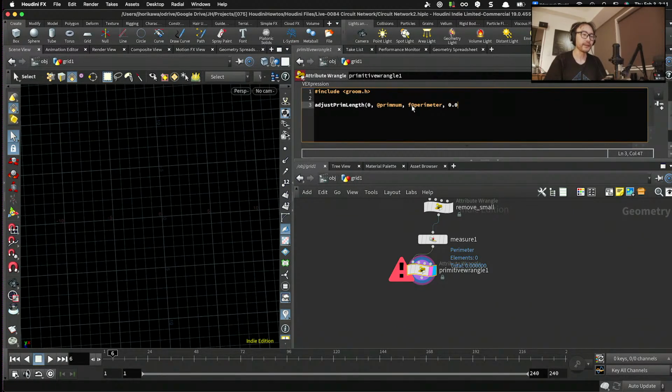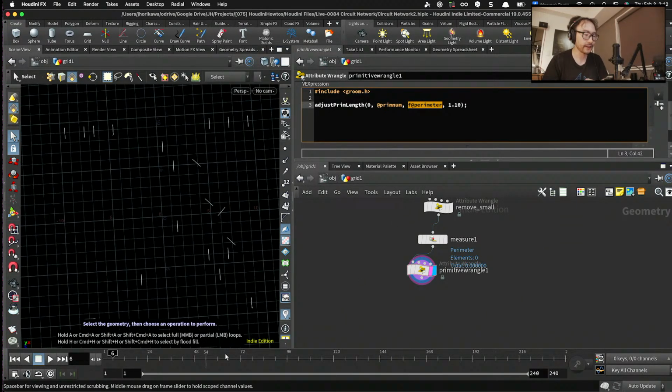If it's 0, then you're going to trim all the curve. If it's 0.1, you're going to grow by 0.1, and if it's 1, you're going to grow the curve by 1. So if you increase this value until the perimeter, you get nice animations growing this curve from start to end. Okay, so what you need to do is to create the values for this one from 0 to perimeter based on the start frame value and the current frame value.